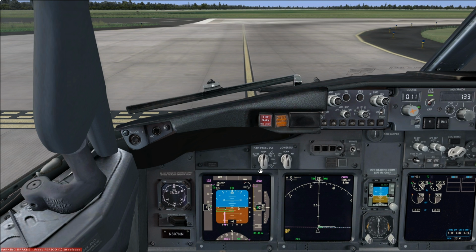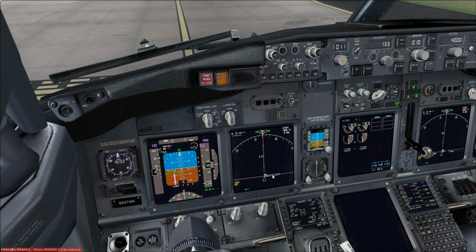Now, how do you know if the PWS has detected wind shear? Well, first, there are two wind shear alerts in most Boeing aircraft. The first alert comes from the PWS system in the form of an oral alert that goes something like "monitor radar display," as well as a visual indication on the nav display that has red markings which kind of look like a fingerprint, I guess you'd call it, that shows the location where the wind shear was detected.